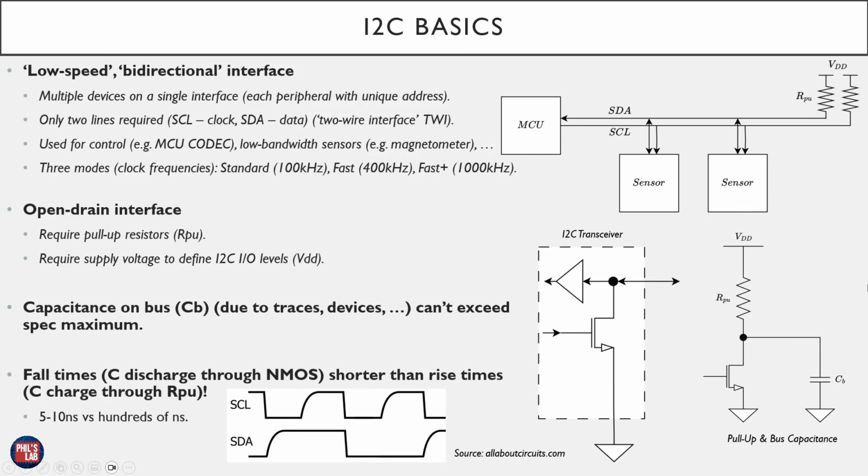We'll go over the I2C basics just to start with. Again, this won't be a very in-depth video on the basics. I'd like to discuss a few other things instead. I2C is the short form for inter-integrated circuit, so connectivity between integrated circuits. For example, if we're connecting a microcontroller to a sensor and we want to get, for example, measurement data from that sensor, an option might be I2C.